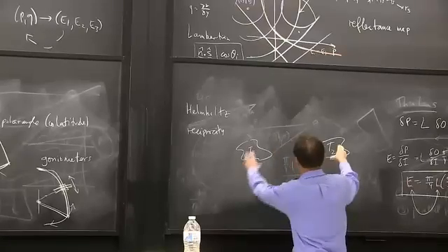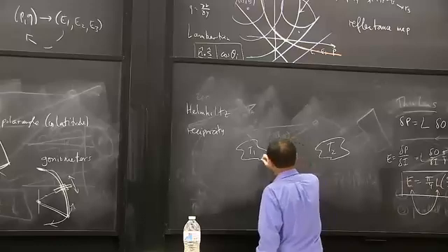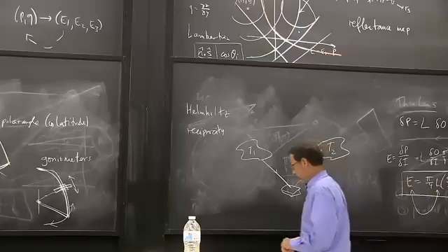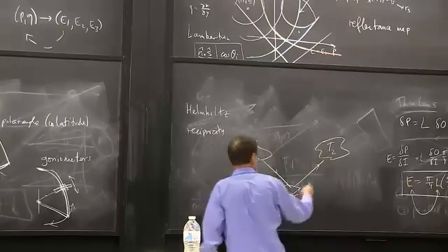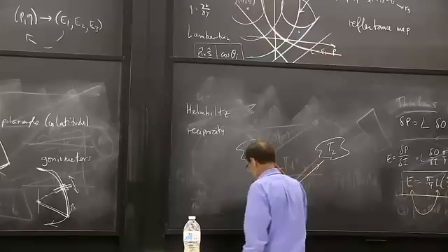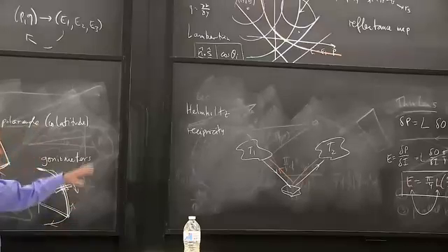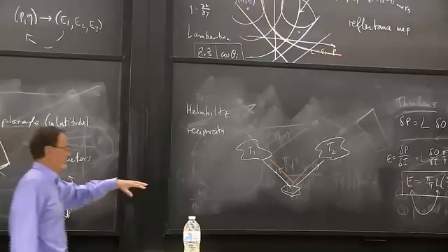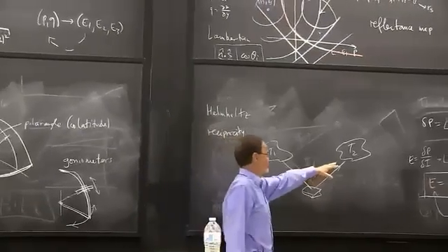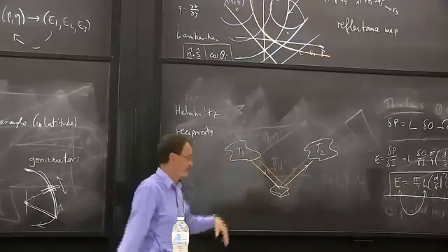So suppose we have two objects at different temperatures, and there's an object patch down here. And so there's radiation coming from one and going to the other. And reciprocally, there'll be radiation coming from the object at temperature T2 and arriving at T1. And it takes a little bit of hand-waving, but basically what it's saying is if it's not reciprocal, then there will be energy transfer from the colder object to the hotter object, which we know doesn't happen.